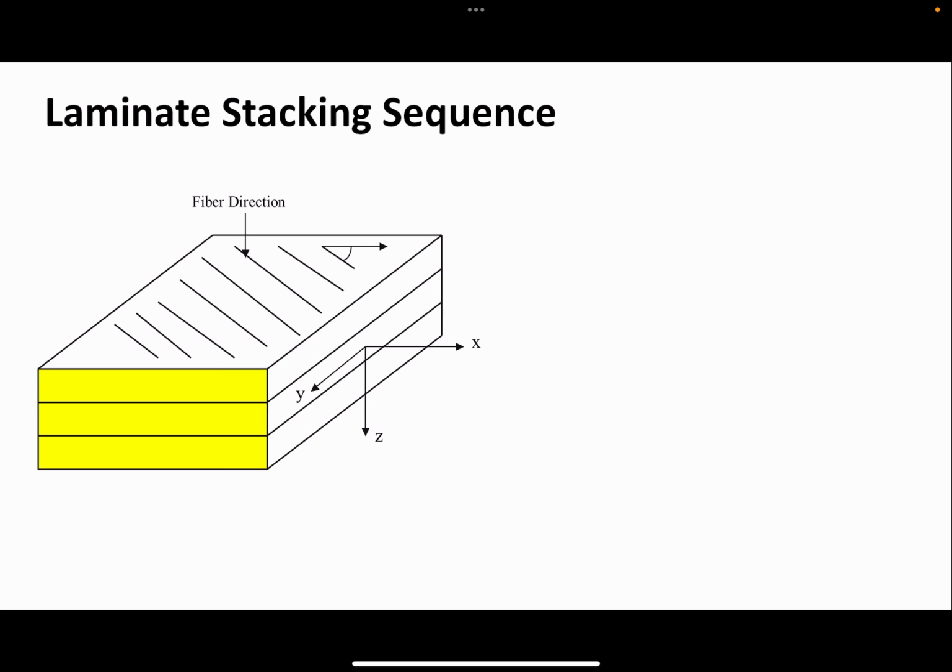So then we come to, as always, how to calculate strains and stresses. Let's say in your beam you have centric or axial loading. Axial load, you all know, goes through the central axis of your structure. In that case, you know how to calculate stress.